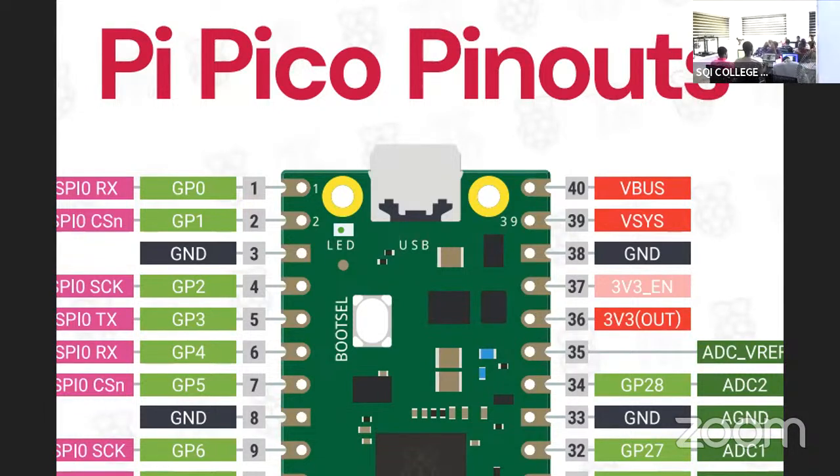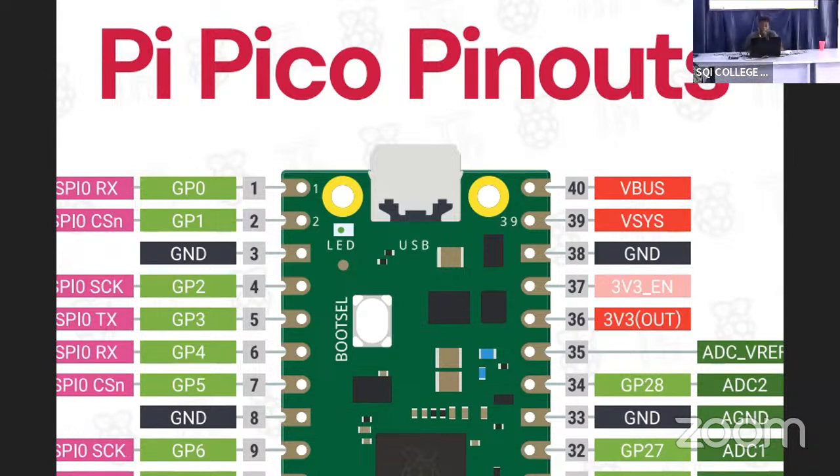All right, so the pinouts on this Pico are labeled under the controller. We'll be referring to them as the class goes on. Now we can see VBUS. On the red side of our pinout, you can see VBUS, VSYS, 3.3 volts out. They are the voltage aspects of the controller. VBUS has the ability to give out 5 volts. VSYS has the ability to take in 5 volts. And the 3.3 volts has the ability to give out a maximum of 3.3 volts, depending on the type of sensor you want to use. So we'll be referencing each of these voltages depending on the sensors that we have on the table.